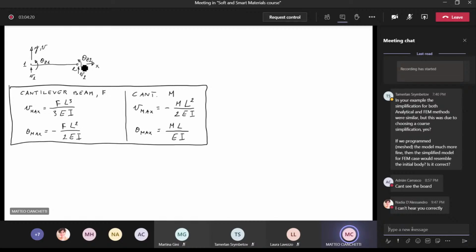Okay, so let's start activating one single degree of freedom at a time. So we are going to implement the rule that I said before. I will repeat it just for you. A column of K, the element stiffness matrix, is the vector of loads at nodes to give the corresponding DOF a unit value while the other degrees of freedom are 0.